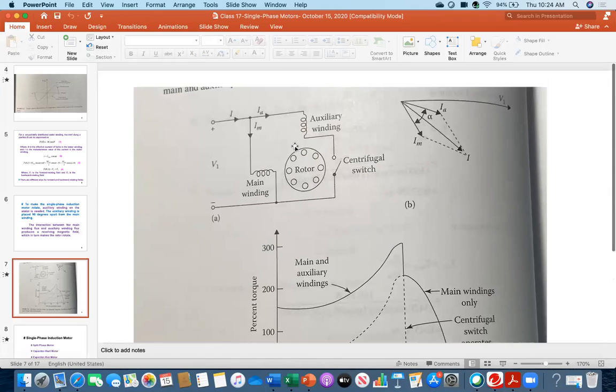So everybody see, first I am drawing this VT, the terminal voltage. It looks like a car because of how I scanned it, but keep in mind this is a straight line. And then, of course, these are the coils. If it is pure inductance, then definitely the current will be 90-degree lagging. So the current should be straightforward here, 90-degree.